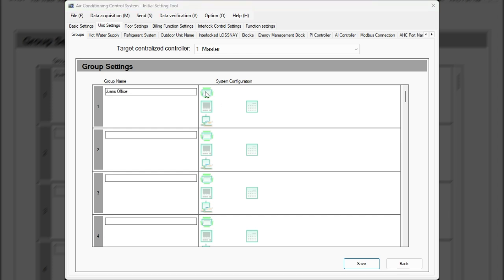And then to add the actual MNet unit, you click the icon. You've got your MNet unit, MNet address there. And then you select the icon. So if it's a PKFY, we can select that wall-mounted unit. And now the tile on the touchscreen and an ICCW will reflect the actual unit.